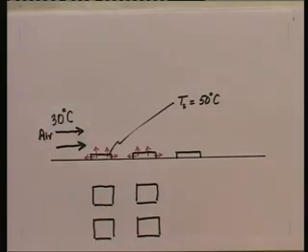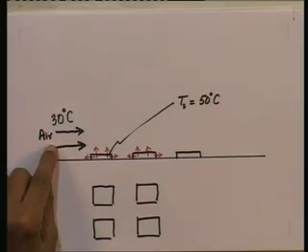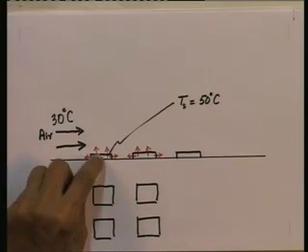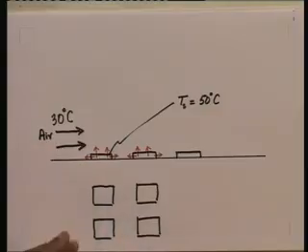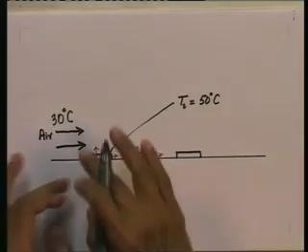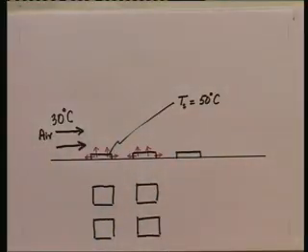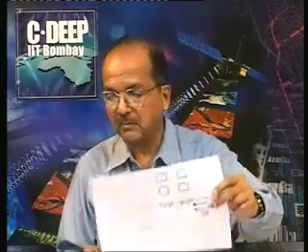Now, the problem before the heat transfer engineer is at what velocity should this air be blown, so that this surface temperature is not exceeded. That is a typical convective heat transfer problem, for which you need equations, data, the flow around the electronic chips and so on to be analyzed. So, here is another example, the cooling of electronic chips, as an example which would be of interest to us as we go along.